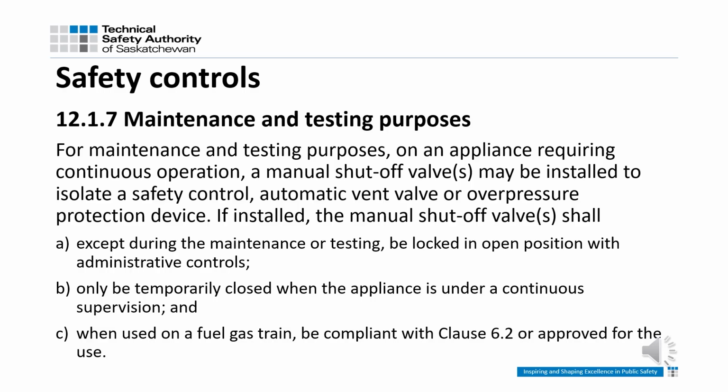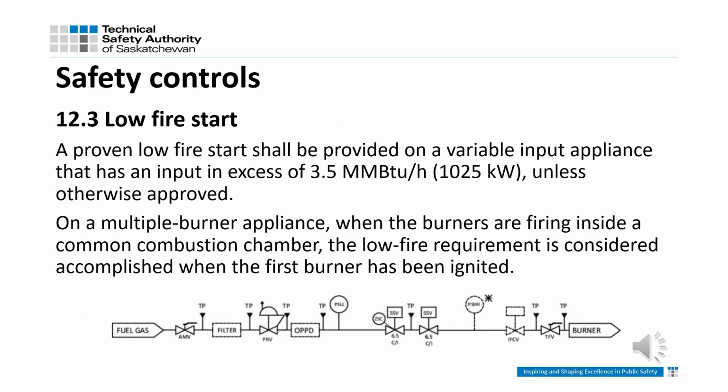12.1.7. Maintenance and testing purposes. This gives the requirements where manual shutoff valves may be installed and the conditions that must be addressed in A, B, and C. 12.3. Low fire start. The requirement for a proven low fire start has increased to an input in excess of 3.5 million BTUs per hour, unless otherwise approved.